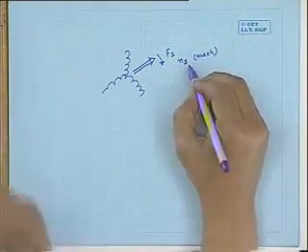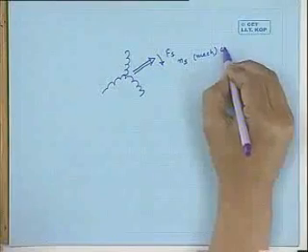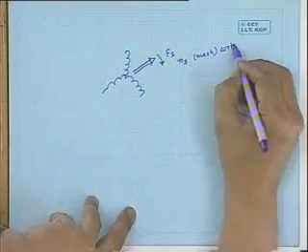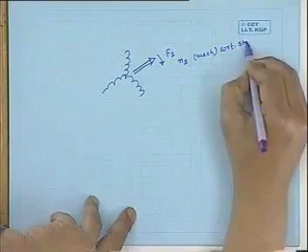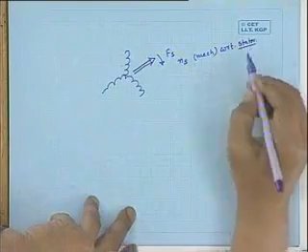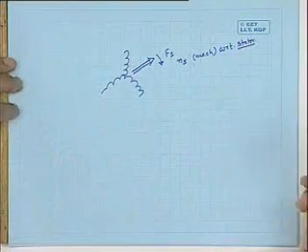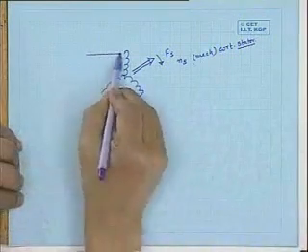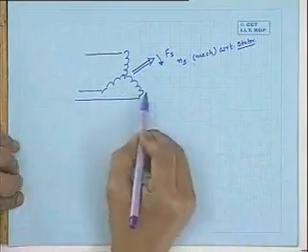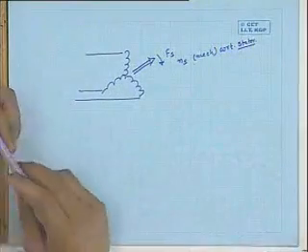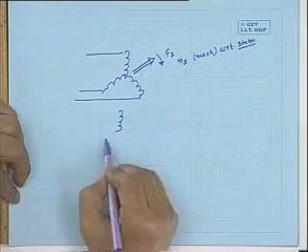Fs, which moves with a speed Ns mechanical. And another thing I should write: with respect to what? I will write with respect to the stator, because the winding is housed on a stator, or with respect to a stationary observer. They are the same thing. So this is connected there.